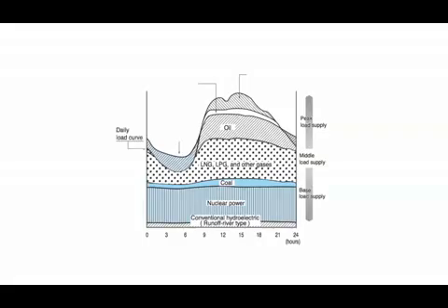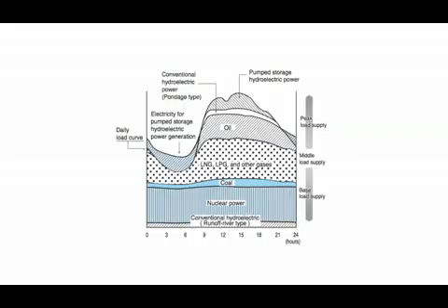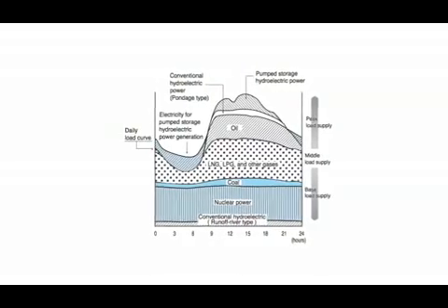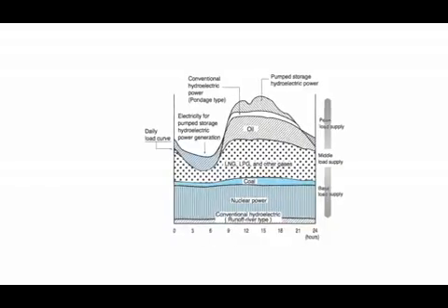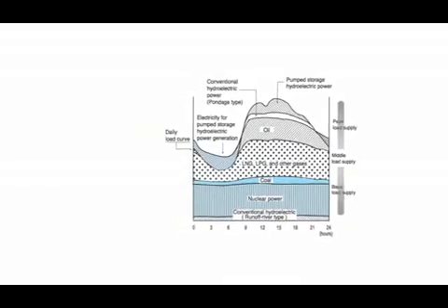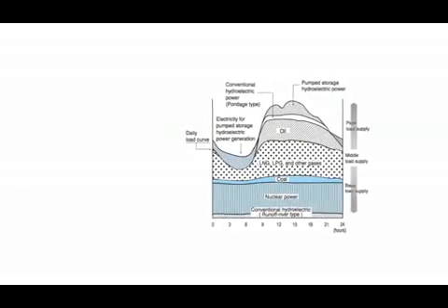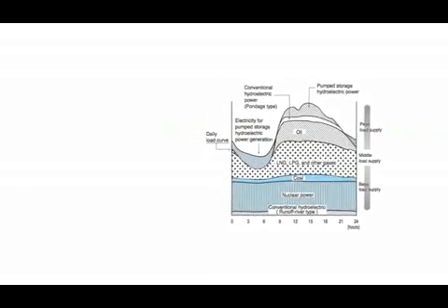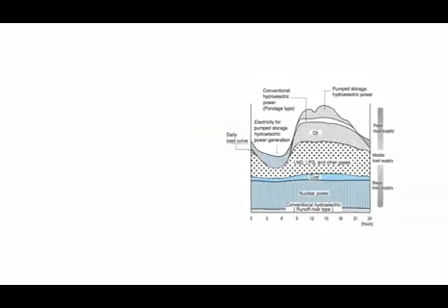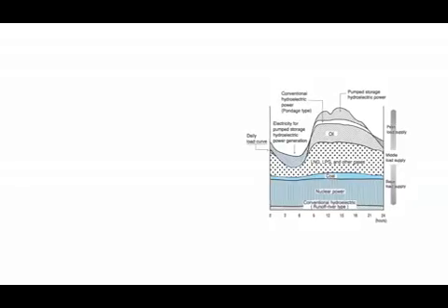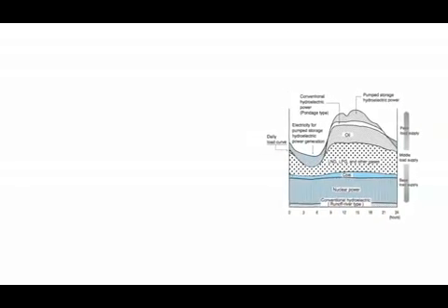As can be seen from the picture, thermal, hydro and nuclear are base load plants. That is, they provide a minimum amount of electricity continuously. The first cost, or the investment cost, of base load plants may be high, but the running cost should be low. Fixed cost is the cost of land, machines and all the installation charges, and running cost is the cost of raw material, maintenance cost and transportation cost.